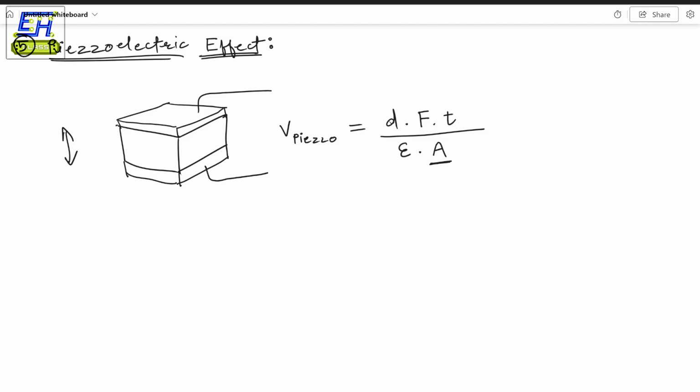And this is where we actually use piezoelectric speakers or piezoelectric buzzers, right? So if you can provide a changing voltage signal to the crystal instead of getting that voltage, so basically like applying an external changing voltage to the crystal, you will see this crystal will physically deform. And that thing will actually generate sound, right? And basically corresponding to the frequency of the voltage signal that you're providing, you will see equivalent audio signal, or sound signal, coming out of the crystal.